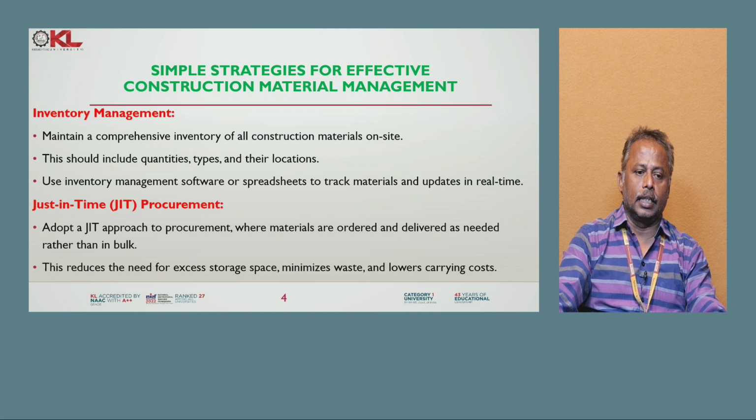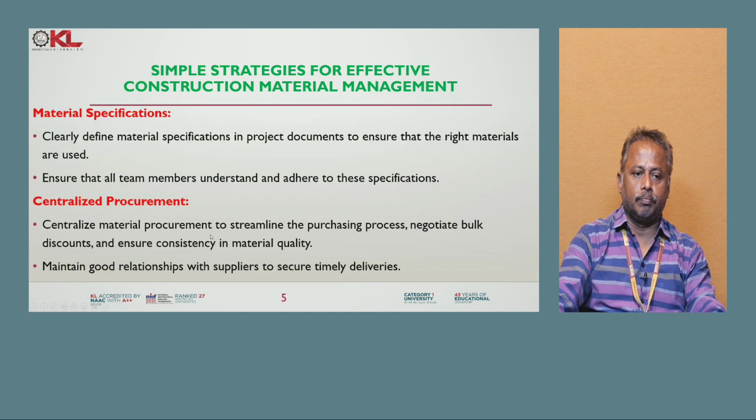Then just in time procurement. We can adopt just in time procurement, where materials are ordered or delivered as they are needed rather than in bulk. It reduces the need for excess storage space, minimizes the waste and lowers the carrying cost.